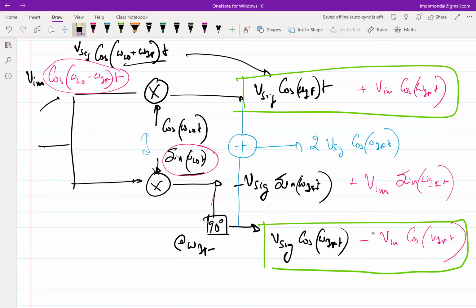Sometimes you can do a bit of both, in the sense that you can have an image reject filter, and we know that none of these filters are perfect. It's not as if this is going to cancel out the entire image. There will always be some residue. You have the filter and then do the image cancellation in digital. That is also possible. So in any RF chain, none of this cancellation is done at once. It's done at various parts of the chain, and you keep cancelling. It's almost like cooking: you have the same ingredients, but when you put them in makes all the difference.